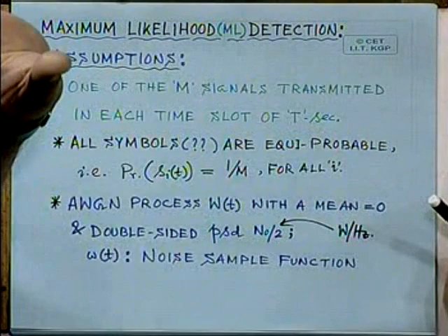If you think back about the correlator structure as per our Gram-Schmidt orthogonalization procedure, we get the correlator output at the end of the observation duration 0 to T. You multiply the signal with the basis functions and integrate, and you get the corresponding coefficients. These are obtained at the end of the integration period of duration T. So the coefficients form the vector basically.